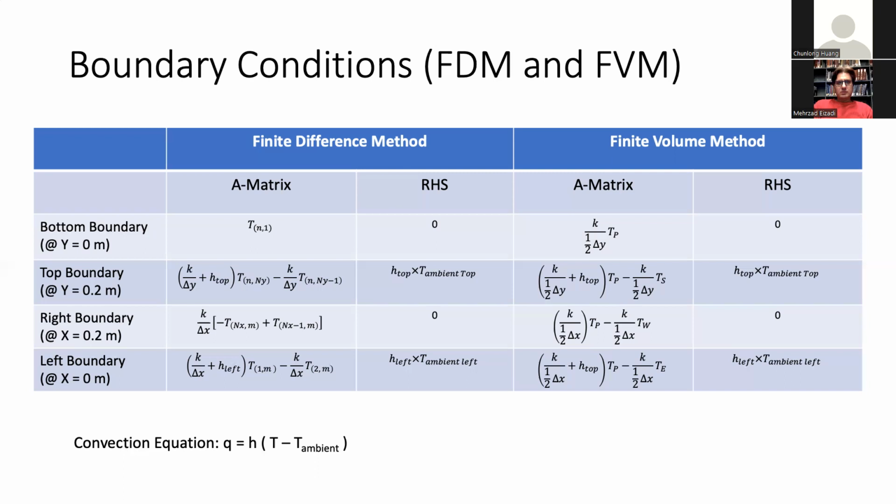For the y boundary side, we have a Neumann boundary condition, which does not have a heat transfer in between. At that boundary, there's no heat transfer there, just because that's kind of the symmetric section. There's a symmetric section right next to it.